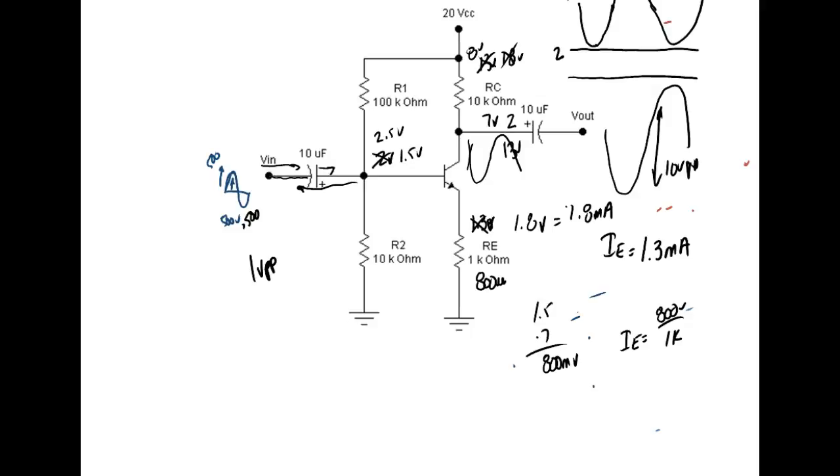So we're going to bring the input signal here. What's that input signal going to do? It's going to change this voltage. Then it's going to come over here. It's going to cause the voltage across this thing to change. Right? You understand? Which is going to cause the voltage drop across here to change. Which is going to cause my output voltage to change proportionally. So did we get a voltage gain out of this? Sure.